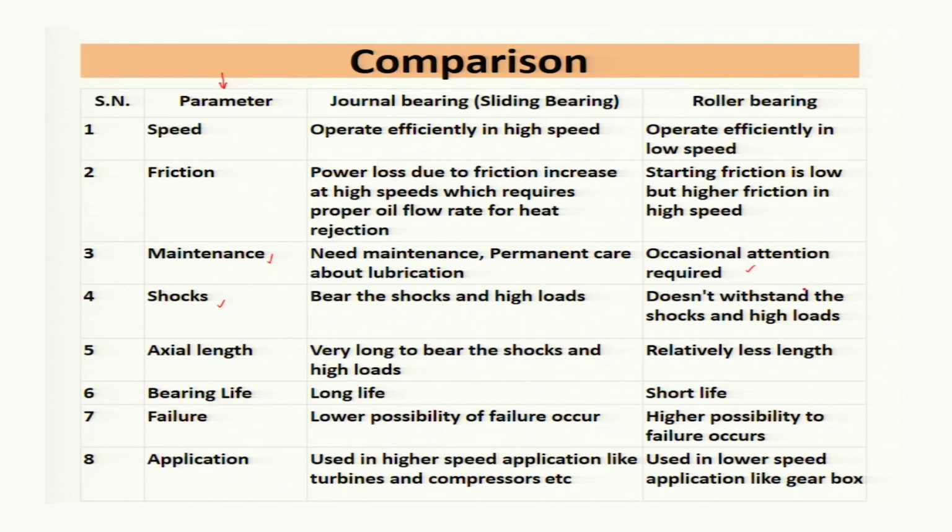But for the rolling element bearing, we have seen that the shaft and bearing are connected with the help of a metallic rolling element, that may be a ball or a roller, and so rigidity is there, and whatever deformation occurs will be elastic deformation. So, the roller bearing does not withstand shocks and high loads. For axial length, the journal bearing needs to be very long to bear the shocks and high loads. In the case of the roller bearing, relatively less length is required.